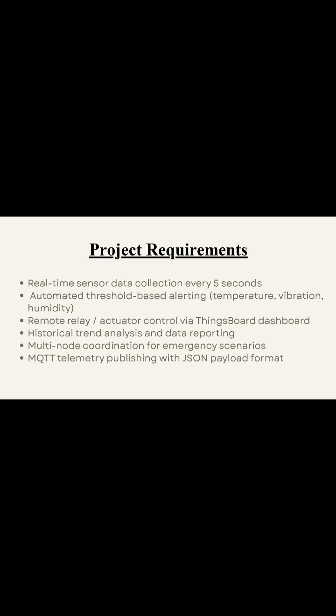Project requirements. Real-time sensor data collection every 5 seconds, automated threshold-based alerting for temperature, vibration, humidity, remote relay or actuator control via ThingsBoard dashboard, historical trend analysis and data reporting, multi-node coordination for emergency scenarios, MQTT telemetry publishing with JSON payload format.